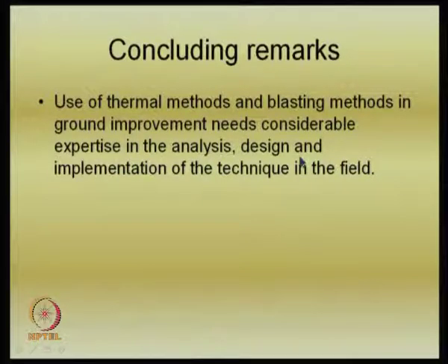So, what I mentioned was that you should do some trials in the field, and then see if the design parameters you have taken are satisfactory or not. Once you do a trial test, back calculate and check your design, then one can implement it in the field, and also verify with a lot of instrumentation to check if the technique worked in the field.